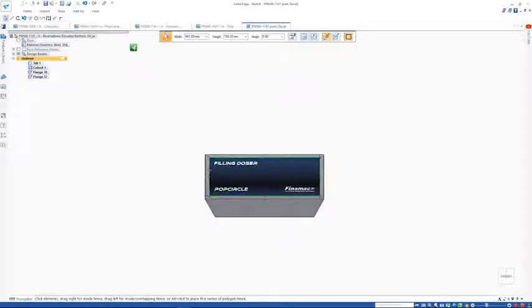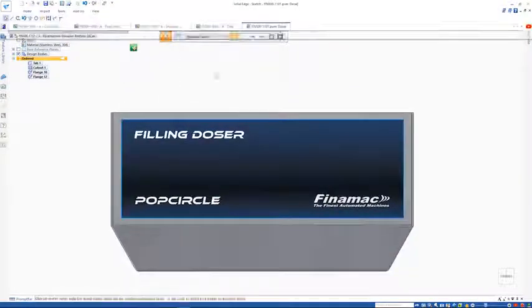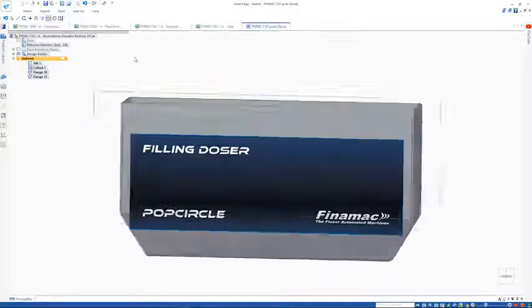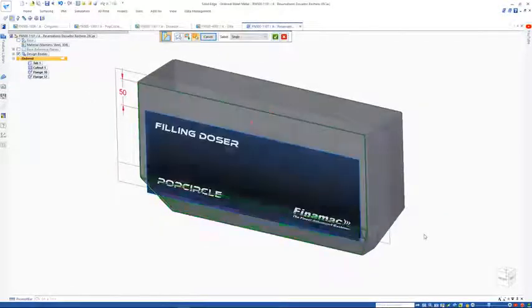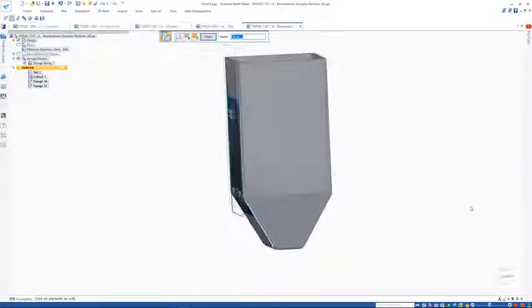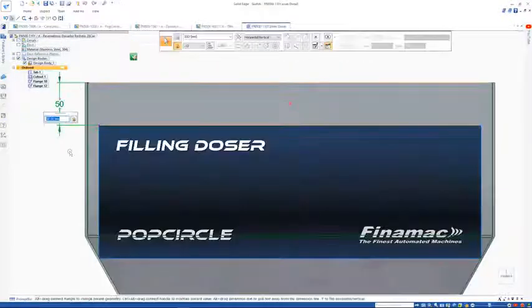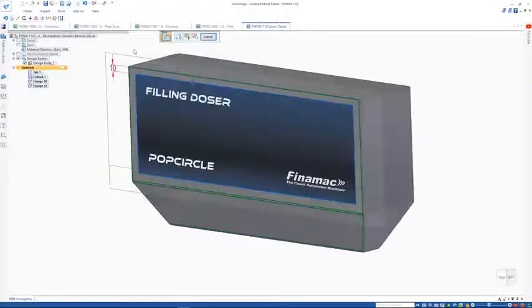Simply select the desired image, define the desired size, and position it accurately using regular sketch relationships and dimensions. The decal can span multiple faces as we see here. However, changing the position of it is as simple as modifying the dimensions or relationships.